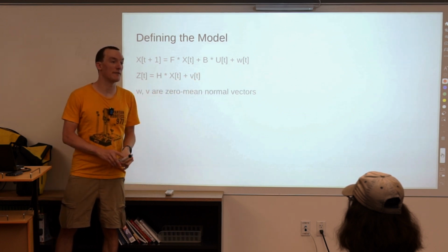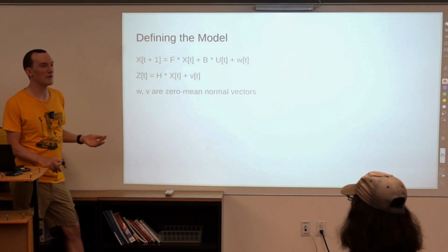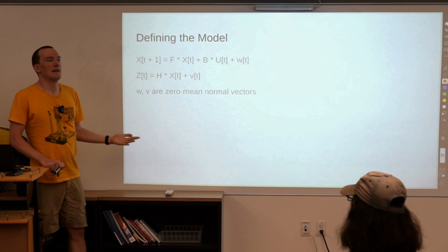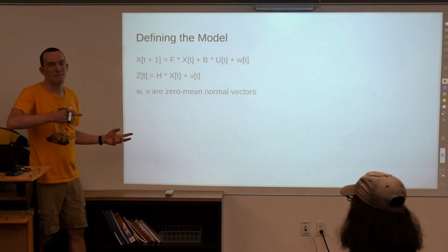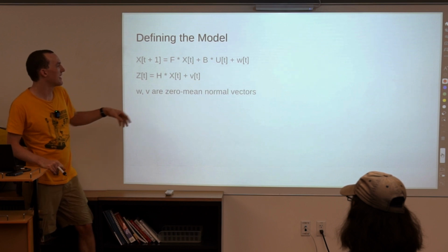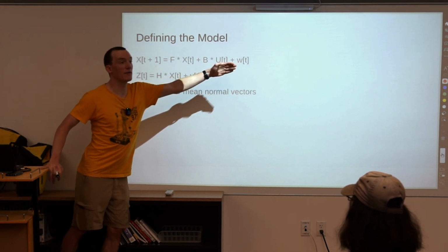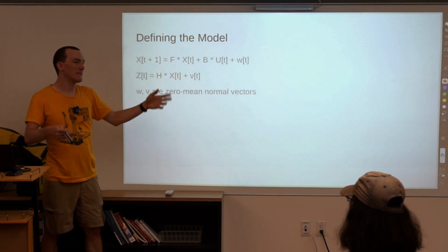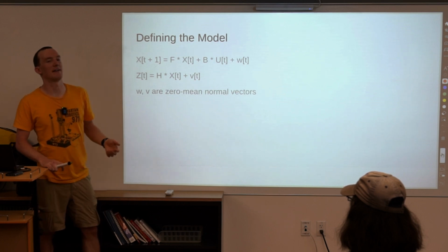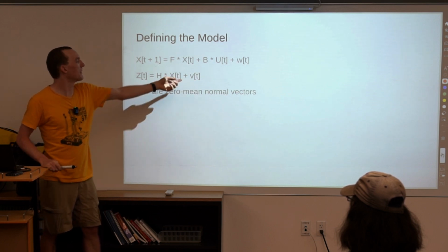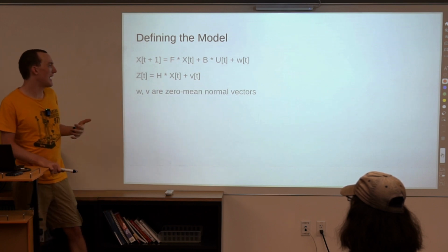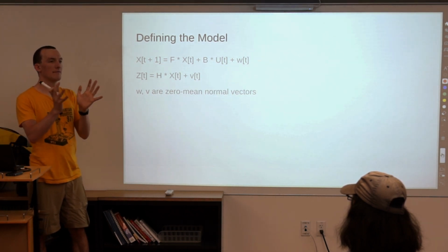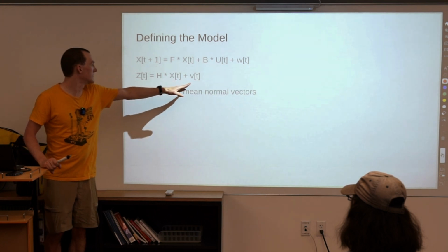of these noises are. So for instance, if you are really unconfident in how your system will evolve, or if there's a lot of uncertainty because you are driving an intake that may have a really bad gearbox, I don't know, then you might have a really high process noise because it will do unpredictable things. If you have a sensor that has a lot of randomness in it, if you have a really low resolution camera and it gives you really flaky readings, you might have a very high sensor reading noise. If you have something that's much more precise, if you have a really high quality gyro and you're estimating the yaw of the robot, then the noise on your sensor reading might be quite low.